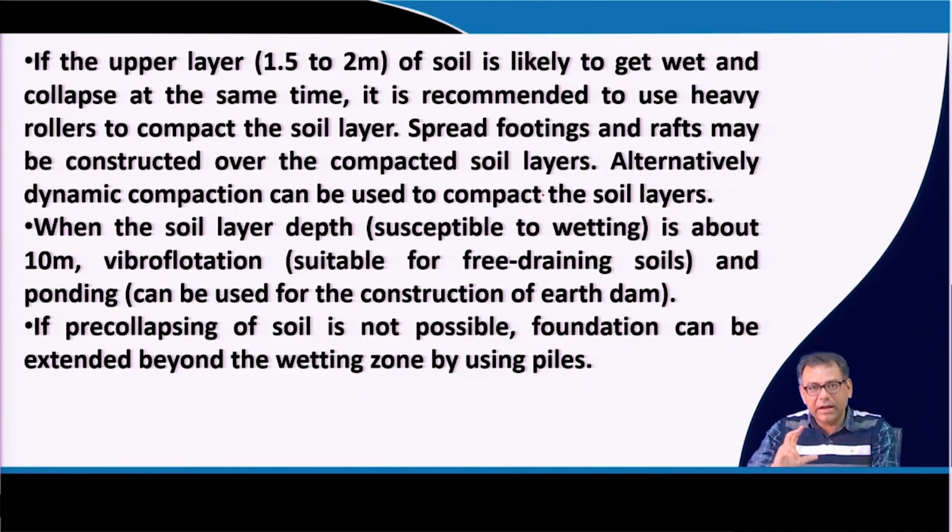Now, if the collapsible soil layer depth is large, say 10 meters, then we can provide vibro flotation, which is suitable for free draining soil, to compact the soil. Or there is another option: ponding, that is, I saturate the soil before the construction.